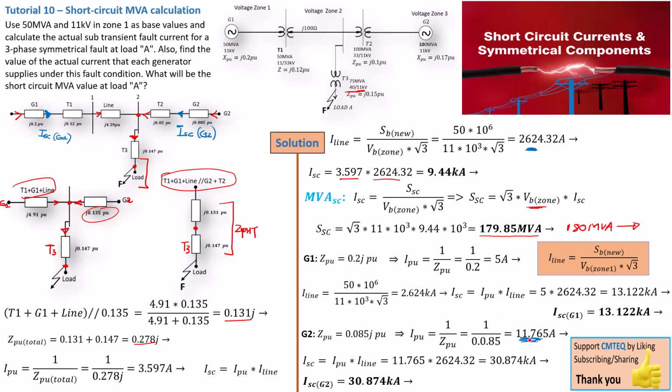And you can also calculate the short circuit current on the secondary of this transformer, on the line here. Now you have to understand that this point here is bus bar 2, which means this impedance here was only denoted for this section.